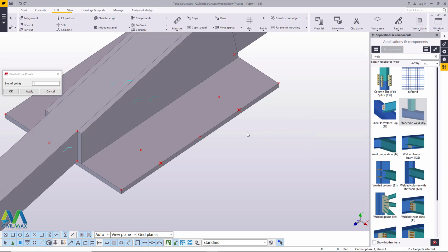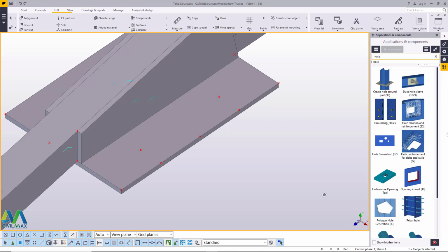Now, without taking a lot of time, what I'll do is very simple. Close this. I'll cancel that. Now I'll go to holes. I just type here holes. Then I'll get the right macro that will help me in creating a hole instead of using a bolt, because if you remove the bolt, the hole gets closed, unless you explode that plate, which is not a good thing. Now I'll just show you how to do that.